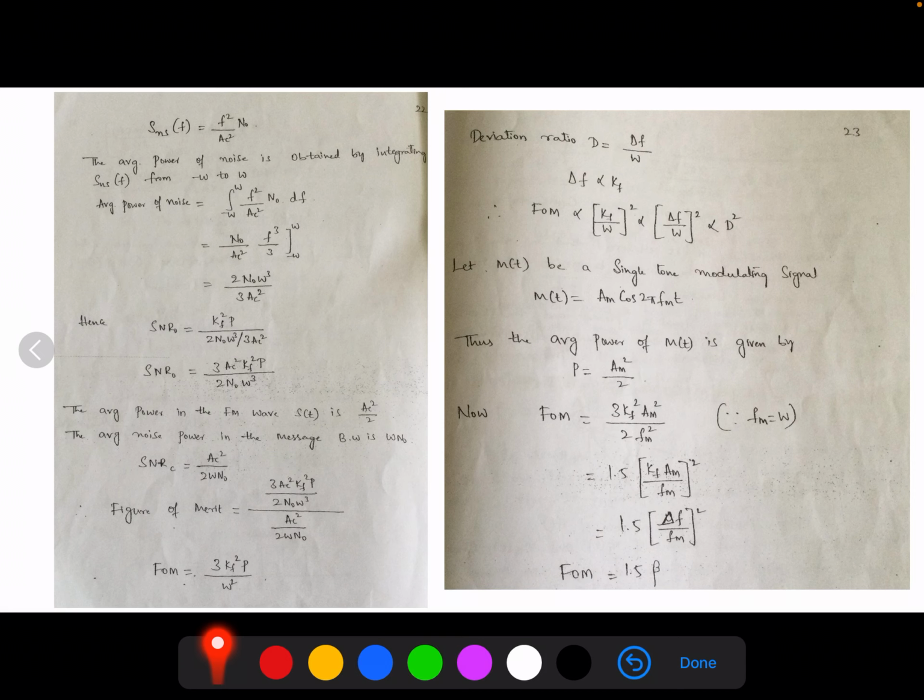When the interference is the stronger one of the two, the receiver locks onto the stronger signal and thereby suppresses the desired FM input. When they are of nearly equal strength, the receiver fluctuates back and forth between them. This phenomenon we call the capture effect, which describes another distinctive characteristic of frequency modulation.